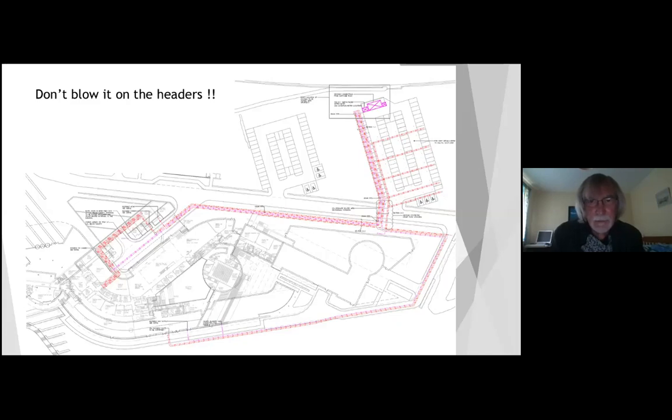Now there's no great big problem with that, but you need to be making sure that that header pipework is of a sufficiently large diameter such that you don't create a huge pressure drop and a huge parasitic pumping energy. The council system was going to be paying something in excess of £16,000 additional electrical consumption, unless the header pipes were bumped up in size. So don't throw away all your good borehole design work and all your active element design work suddenly in the header design.